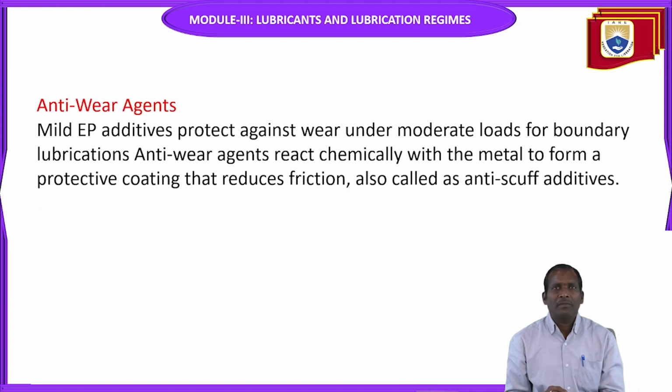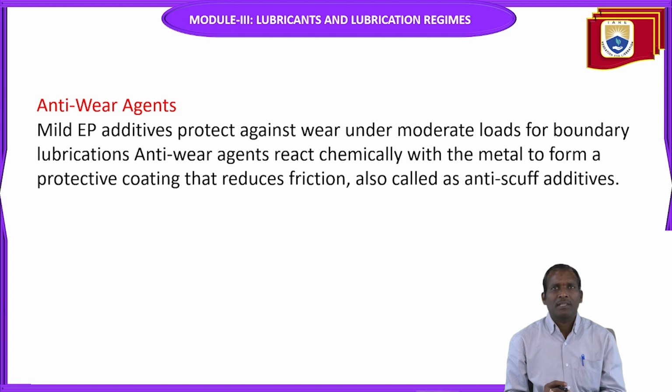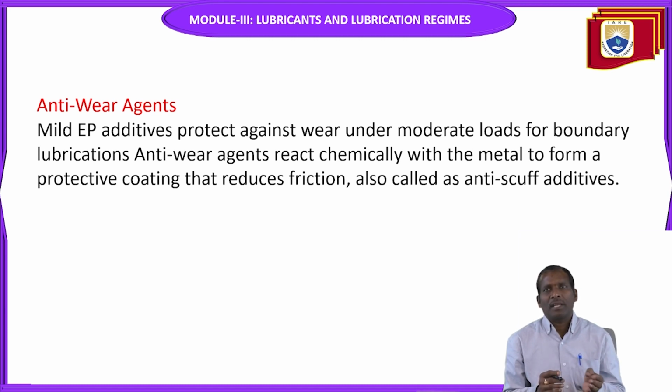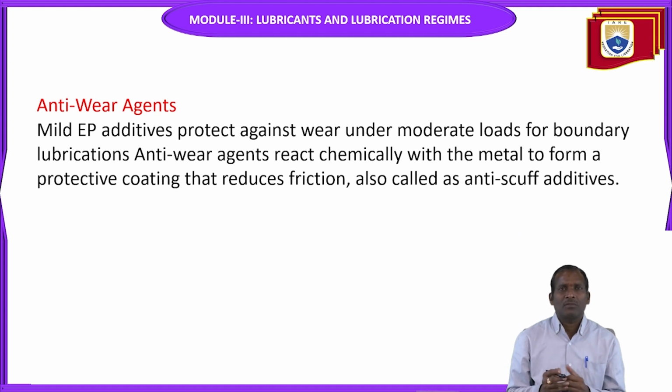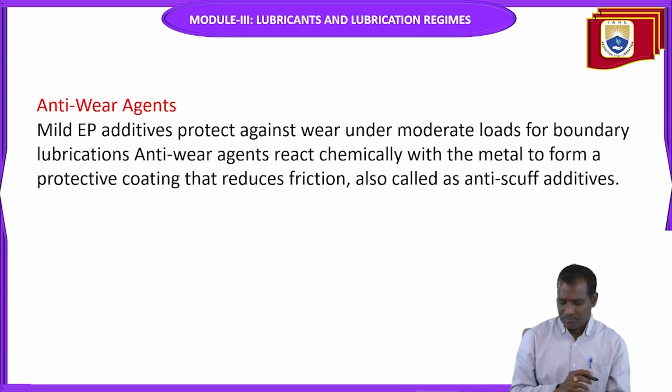So next, anti-wear agents. Mild EP additives protect against wear under moderate loads for body lubricants. Anti-wear agents react chemically with the metal of the component to form a layer, a protective coating, and this reduces the friction. They are also called anti-scuff additives.